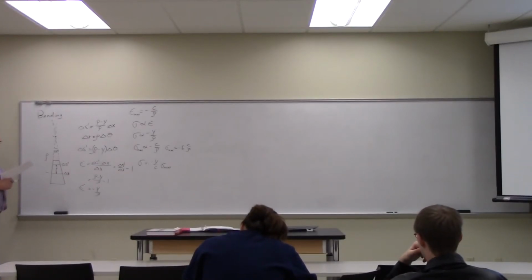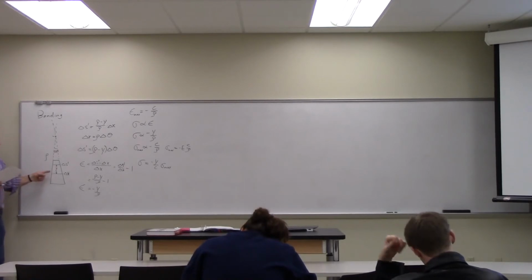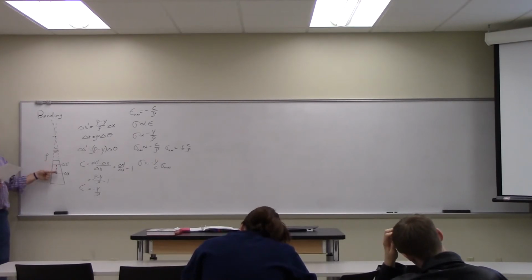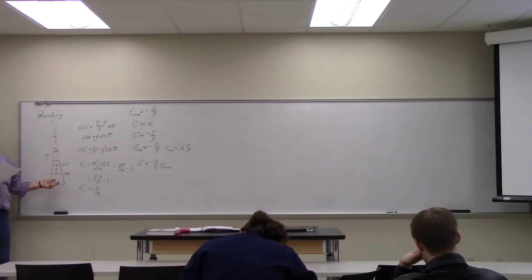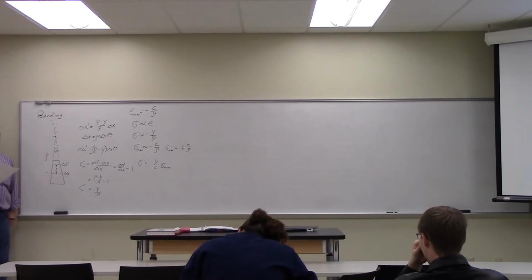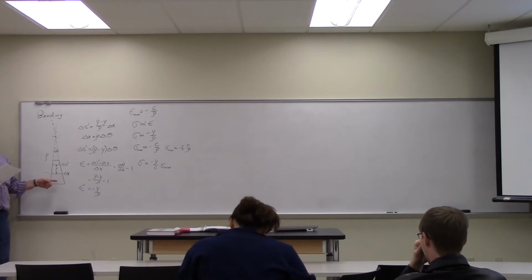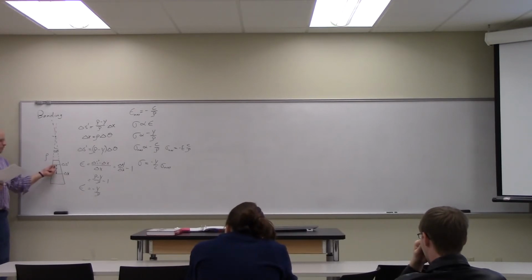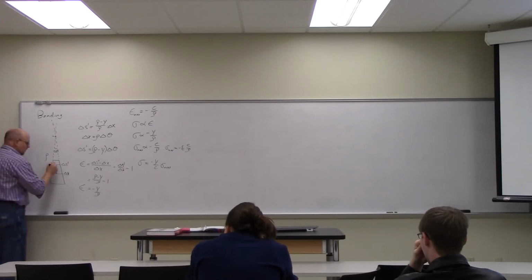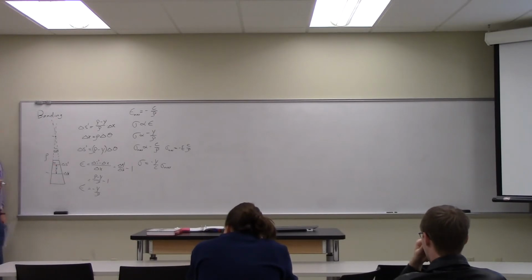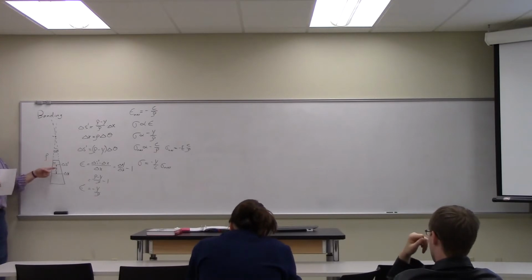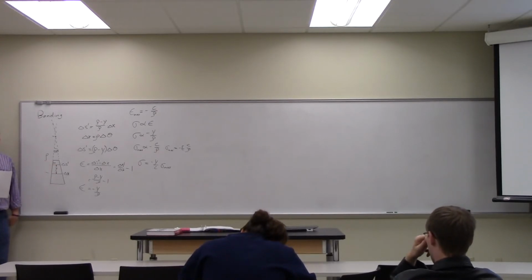Okay, so a couple things to note. If you think about it, think about each element in this little wedge. Every element in this system experiences only normal forces. There are no shear forces in this system. Every little block, if you went through and looked at every little cube of material, it is only being squeezed in this direction. It's only experiencing a normal stress. There are no shear stresses in a bending configuration.